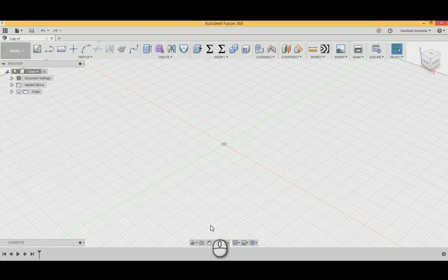I'm gonna do it as a loft, because loft is really cool. So this is what we're gonna do. We're gonna create a circle, and then we're gonna create another. Remember I told you we can create more than one sketch plane. We're gonna create a sketch plane up here, create another circle. Then we're gonna loft from that circle to here. It'll be right on the money. It'll be a solid.